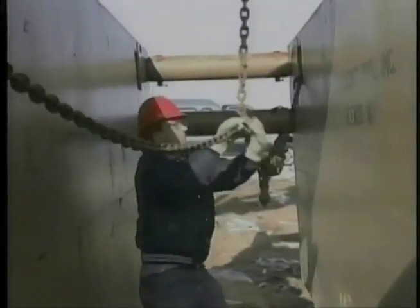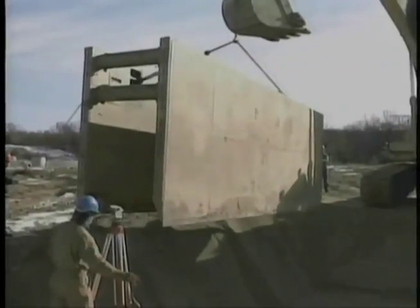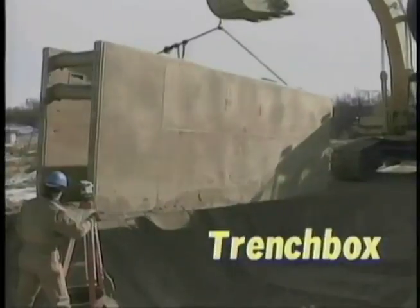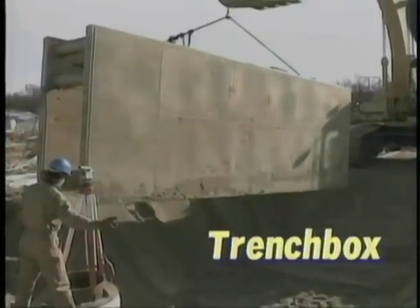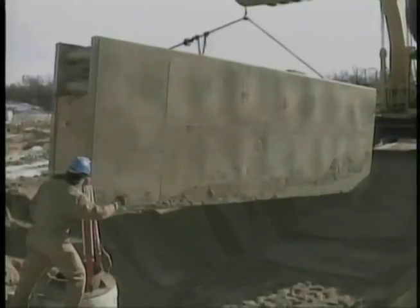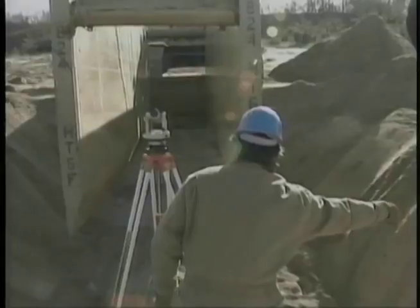In installations where limited work area or unstable soil can create a cave-in hazard, a protection system for workers is mandated by OSHA. Contractors usually select a trench box because they are easy to install, can be moved easily as the pipe laying progresses, and are effective worker protection systems.